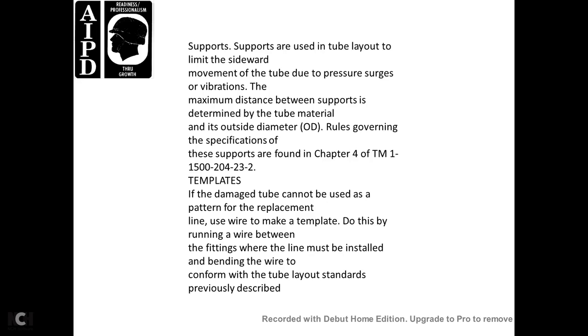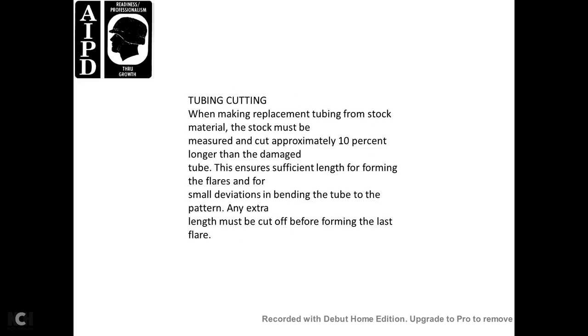If the damaged tube cannot be used as a pattern for the replacement line, use wire to make a template. Do this by running the wire between the fittings. The wire must be installed and bent in conformance with the tube layout standards previously described. Tube cutting.